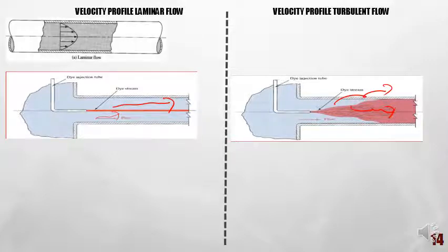If you check here, the velocity is reduced in the area near the surface of the pipe, but it increases in the middle of the pipe. Why? Of course it relates back to the friction near the surface of the pipe.